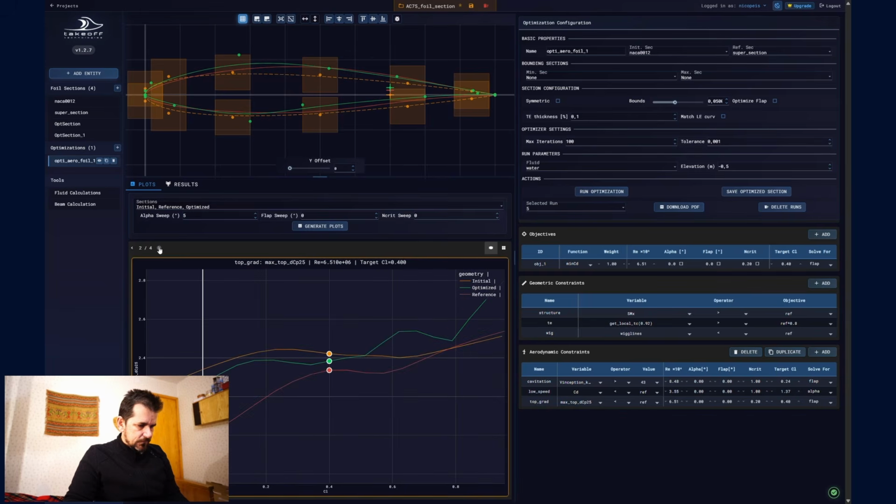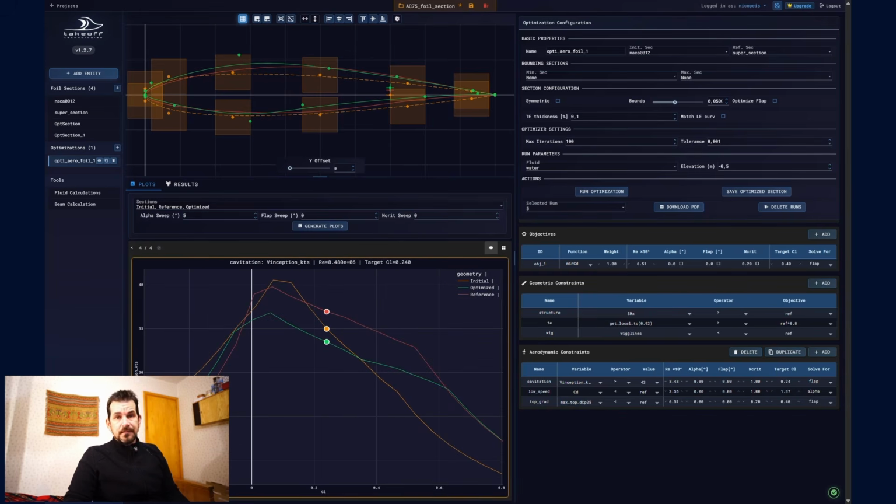So here we have the inception speed. What does this graph mean? We have the CL here varying, and here is the inception speed. This line is marking when the cavitation is happening. So when we are at CL 0.20, what we say here, 0.24, this green foil will be cavitating at 34 knots. So we want to push this cavitation limit up to really high here.